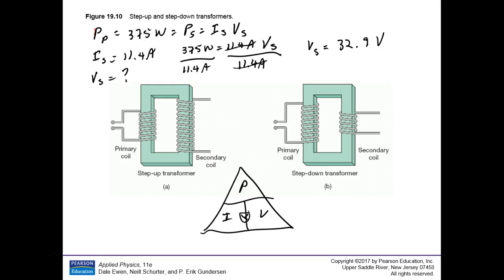Now they say at the top of the next page, 535, good transformers are more than 98% efficient. Very important in power transmission. It's impractical to generate electricity at high voltage, but high voltage is desirable for transmission. Therefore, you generate it at whatever is most convenient. Step it up with step-up transformers, which are very efficient.